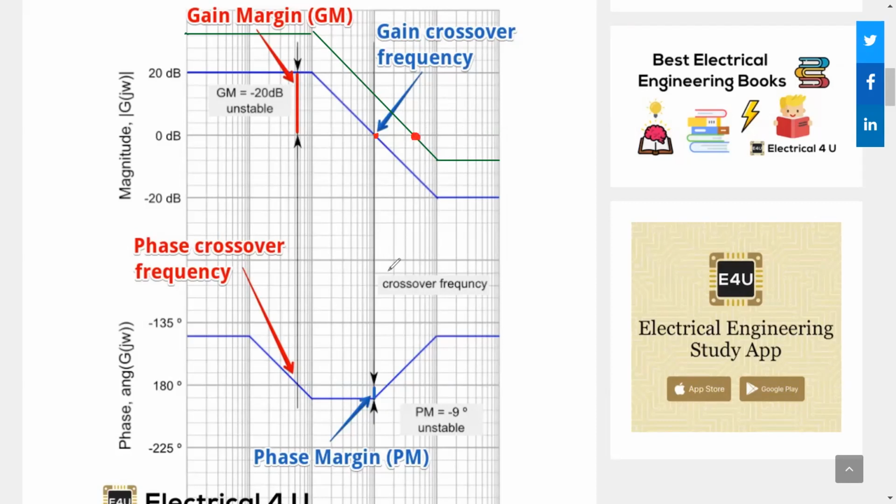Looks innocent enough, right? It's just a shift by phase. But please notice that for this danger point, here downstairs, the phase margin is completely different. What used to be -9 degrees margin became +20 or something.